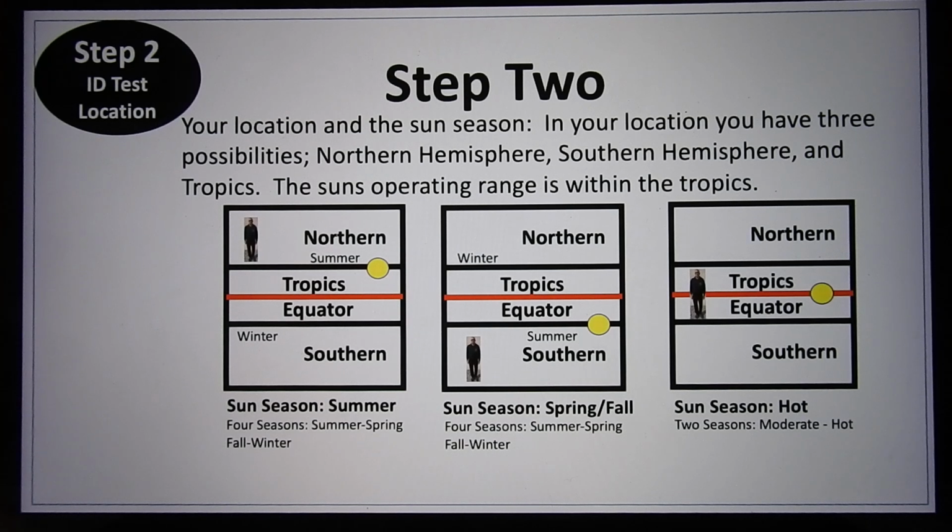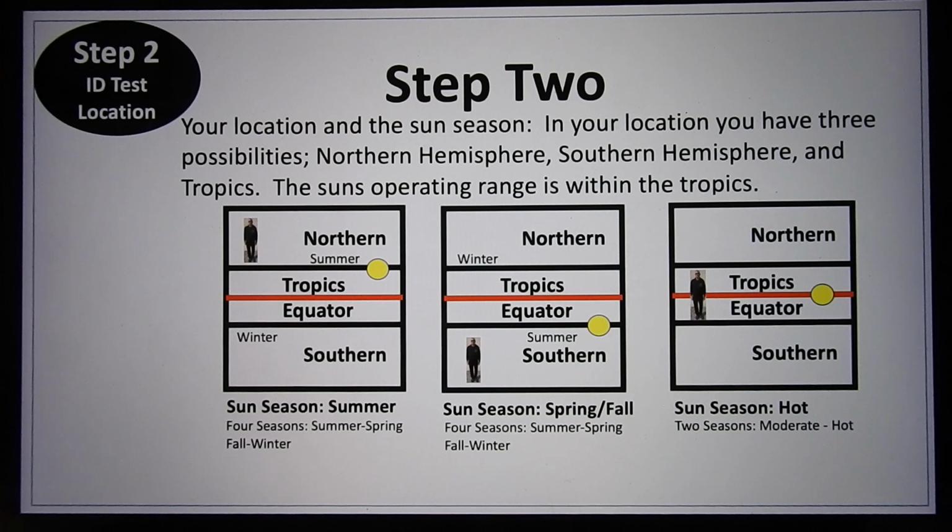If you get readings over 45 degrees for the 45-degree sector test, you're measuring from a flat surface, not a curved surface, because you can't obtain that angle from a spherical surface. It's just too high. And again, we need to know our location to help give us the answer to that.